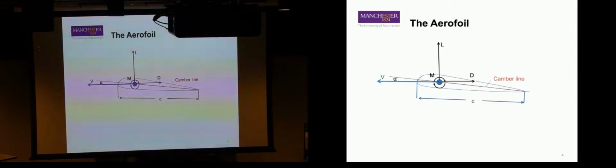Where might we use a negative cambered airfoil? Not necessarily on an aircraft. What application might you think a negative cambered airfoil might be used for? Yeah, so the wings in Formula One and spoilers and stuff on sports cars, those are negatively cambered airfoils. The only difference is you just flipped a positively cambered airfoil upside down because we want to generate downforce. Okay?